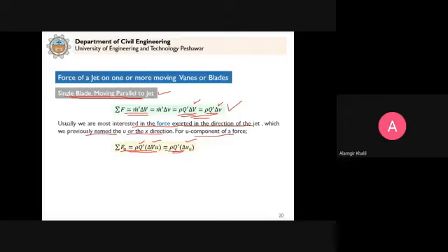We will solve a problem, it will be further clear to you. Clear? Similarly, we can use this expression, and q dash will be equal to a1 into small v1, because this is equal to capital V1 minus u. So this you can also use to calculate the force in the u direction acting on a single moving vane.